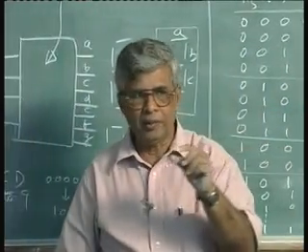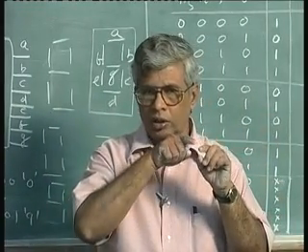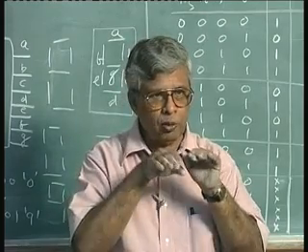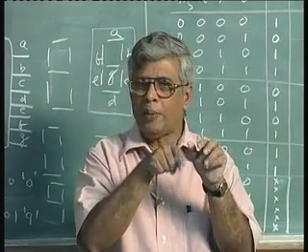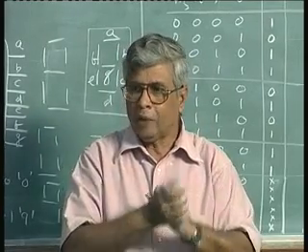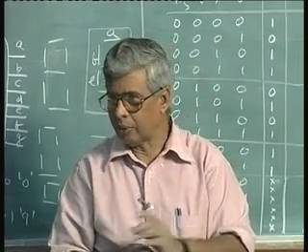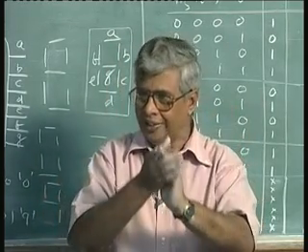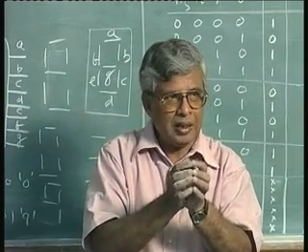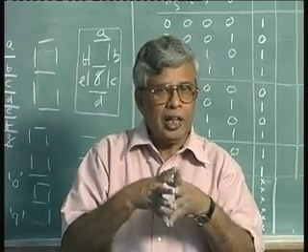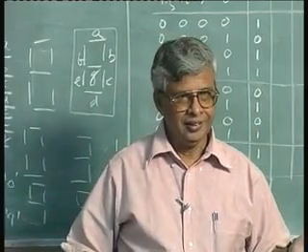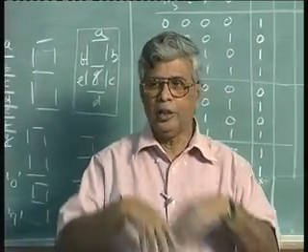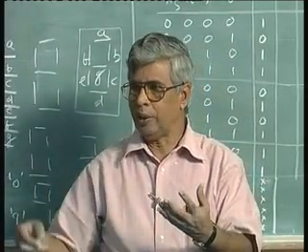Each segment will have an OR gate into which many AND gate terms will be feeding in. Many product terms will be feeding into the OR gate. If one of these product terms is common to 3 or 4 or even 7 or whatever, that part of the hardware, the AND gate combination, need not be repeated for every segment. You can go one step further and see, even deliberately reread the map, not the most optimum way. Do you understand what I am saying? Do not read it the simplest possible way. You see how many common terms I can make. Make as many common terms as possible, and the rest of the terms which cannot be accomplished as common terms, only those terms you make unique for each of these displays.